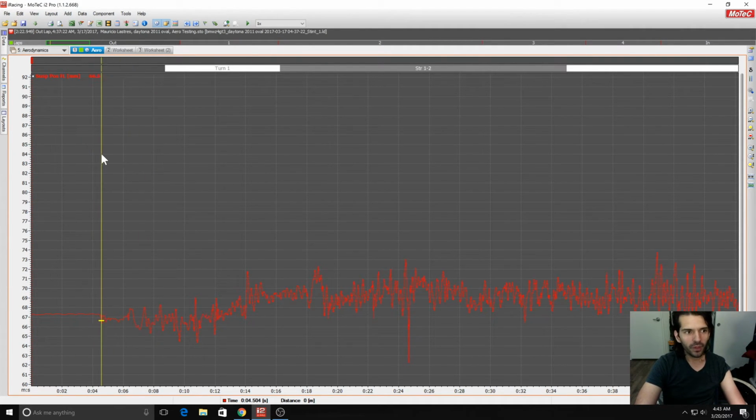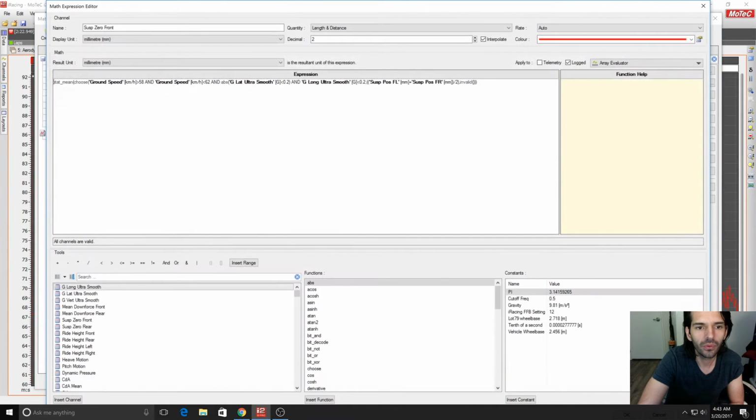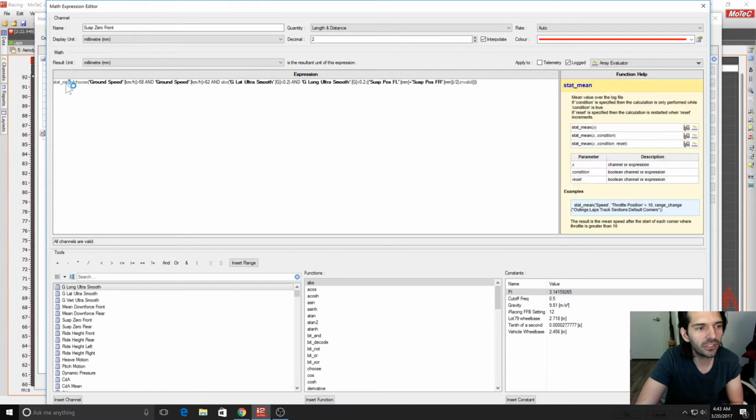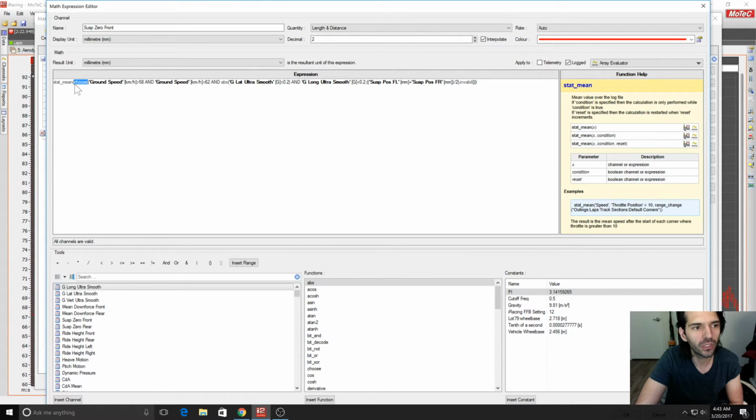So I'm going to do more of the testing, but let's look at, like I said, you have to zero the suspension. So let's see how we did that. Here it is. You have to make it a constant value. So I made a channel called suspension zero front, statistical mean, and then we obviously have to use our choose function.